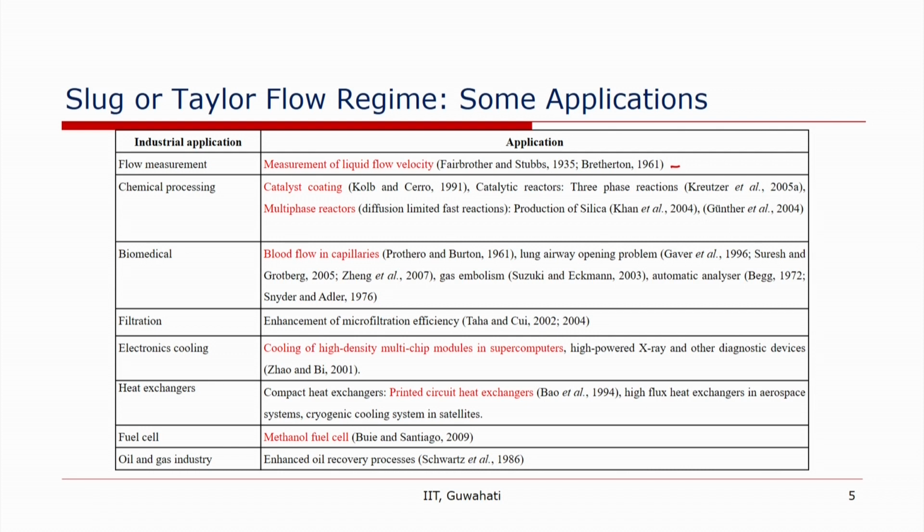If you look at gas liquid reactions in microfluidics or in microchannels or chemical microprocessing, then about 80 to 90% of the work that you will observe is being done. It might be a gas liquid flow, or liquid flow, or sometimes even gas liquid solid flow. Most of the work is being done in the Taylor flow regime. So it is very important to understand the hydrodynamics in the Taylor flow regime.